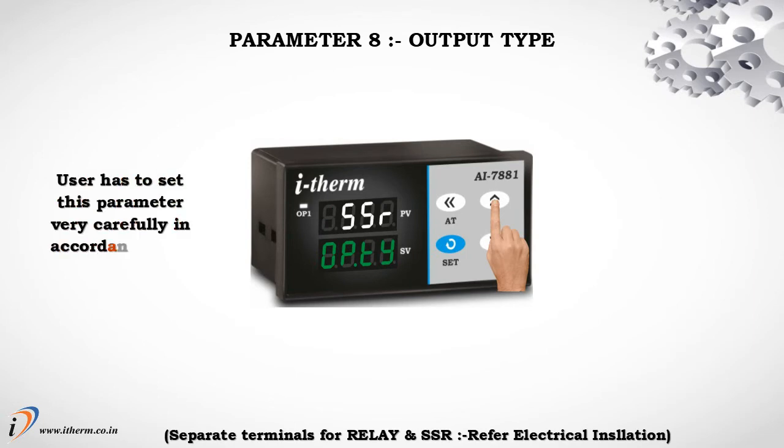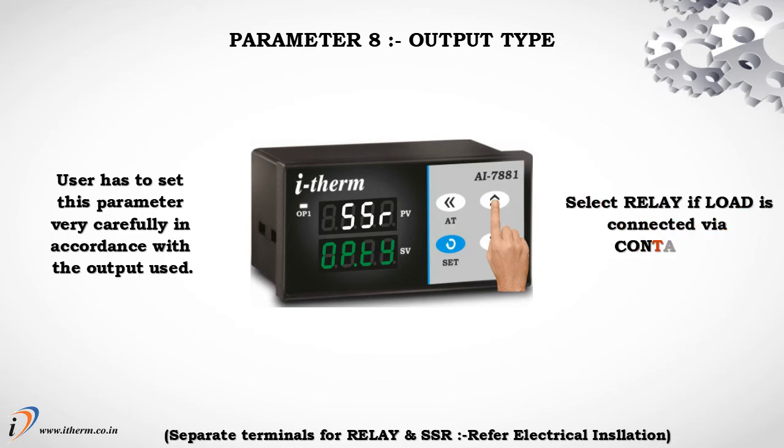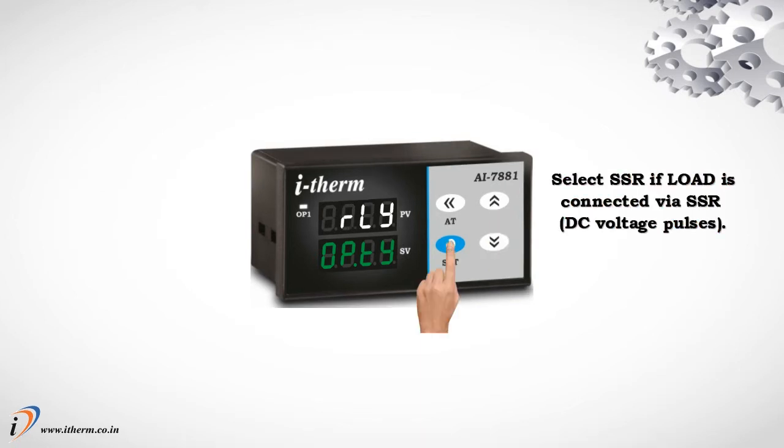The user has to set this parameter very carefully in accordance with the output used. Select relay if the load is connected via contactor. Select SSR if the load is connected via SSR.